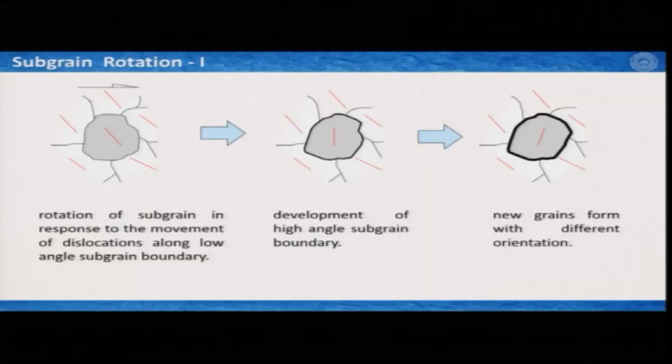If you see some sort of little notch or little bulge from one grain boundary to another, first you must conclude that this is a deformed microstructure, and then you can also conclude which grain had higher dislocation density compared to the other one.